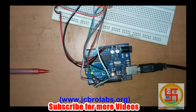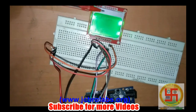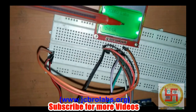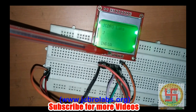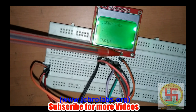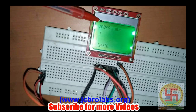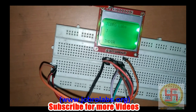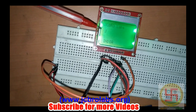So this is our hardware setup, and here we have our Arduino, and here we have our Nokia 5110 LCD. And in this LCD the pins are connected as we discussed in our diagram. This is VCC, ground, and then this pin is connected to pin number 7, and in a sequence like 7, 6, 5, 4, 3, and the last pin is the backlit LED, and it is displaying JCBRO labs and J and then India as we wrote in the program. So this is how we can display any characters or any sensor data or any other information on this Nokia 5110 LCD.